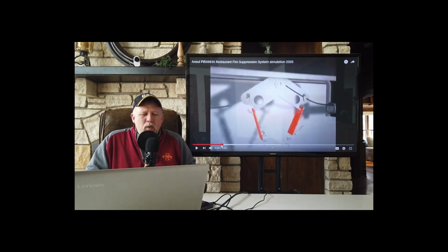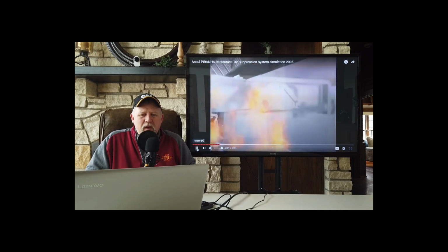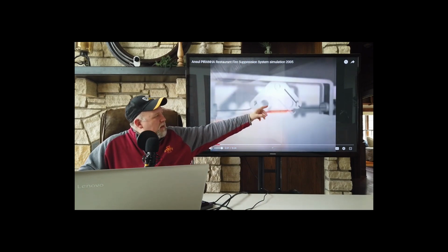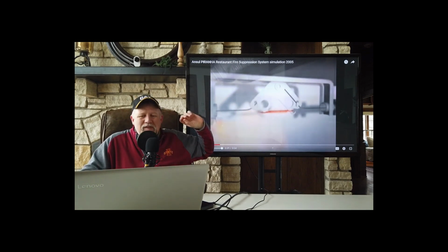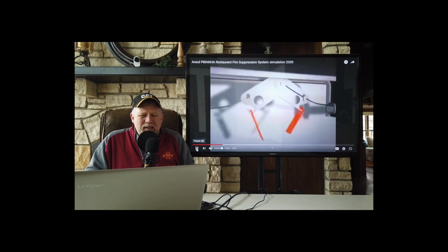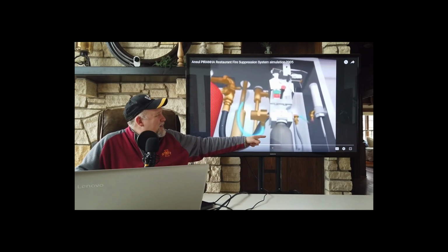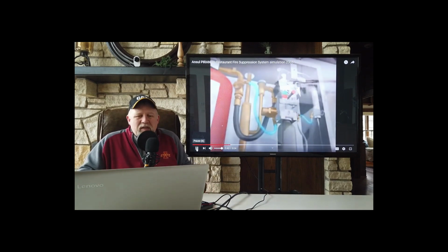So here, within the hood itself, if you go back to about 30 seconds into this video, there is this little spring-loaded plate that has solder in it. Once it heats up to a certain temperature, that plate is going to break. Once that breaks, it is going to discharge the propellant into the fire extinguishing agent.